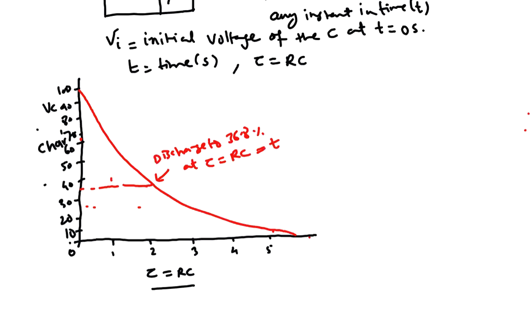And at this point somewhere you say that the capacitor is discharged to 0.7%, which you can say is fully discharged at T equal to 5 times tau. So when you have 5 times the RC time constant, you will have the discharging curve.